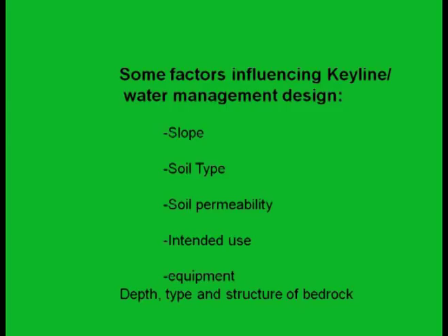Nope. If you're going to have extra water soaking in, and it's certain kinds of soil, most specifically what are called dispersive clays, you get that clay wet, it's like yogurt that you shake and it'll pour right out of the bucket. So you want to be aware of your depth, type, structure, bedrock, and all these other factors. We don't have enough time to get into that.